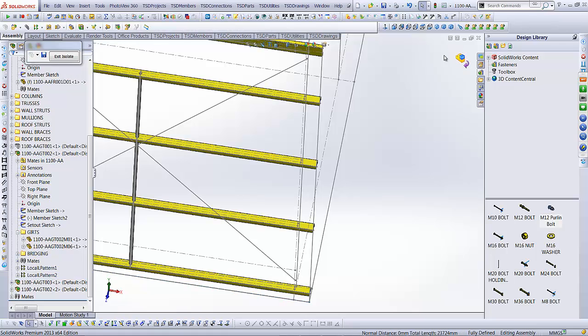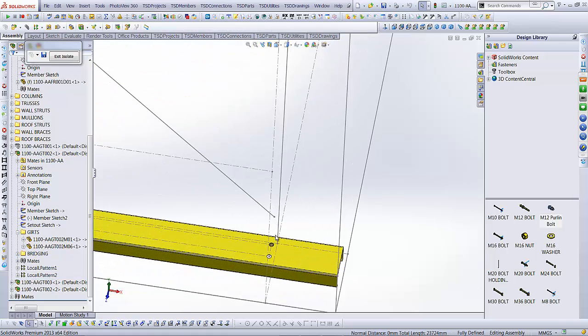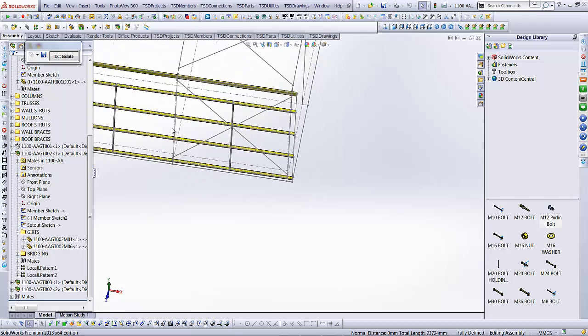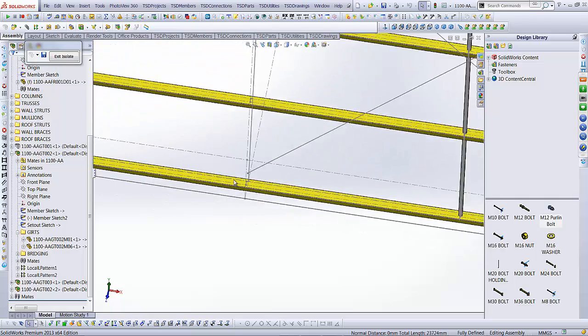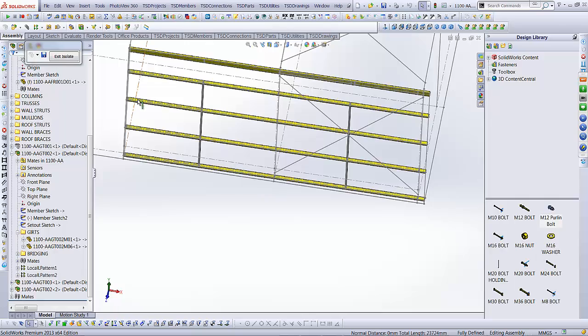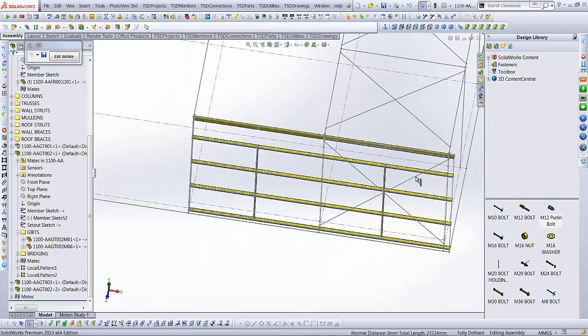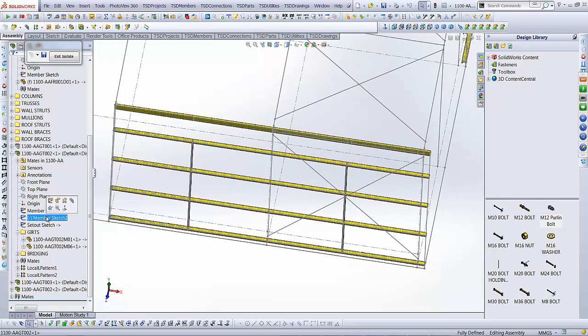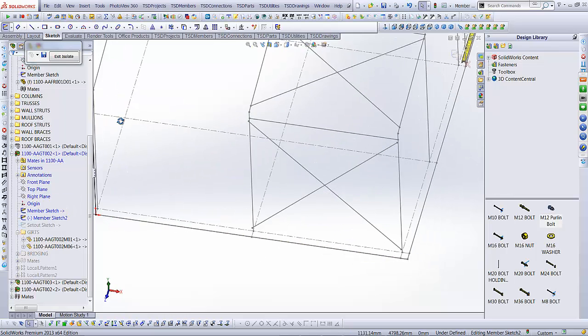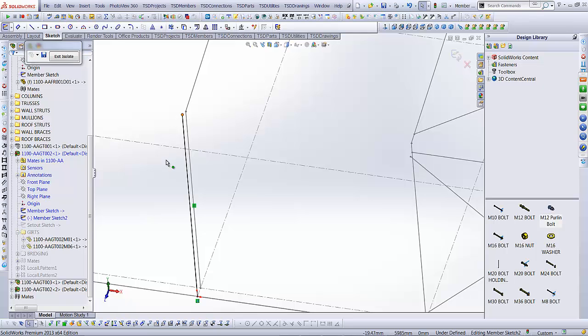So now the driving sketch is updated, and our holes and everything line up with our columns. So if a bay changes, that automatically updates. Our bridging will automatically update now, because the bridging itself is centered, and everything is now snapped on apart from our vertical sketch, which we need to snap onto our driving sketch.